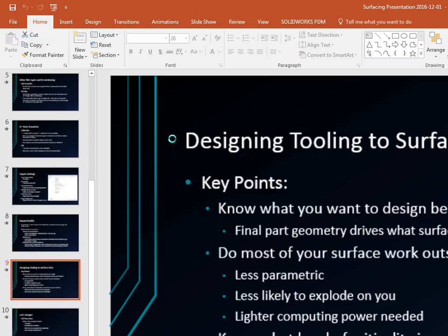That's the way you've done it, where you've trimmed all the bodies. Okay, your radius, or your variable radius. There it worked. You just select them all. That's weird. So if I did select tangent and then go into fillet, the variable radius, it's more likely to work. I don't fillet surfaces much. I usually wait until it's in the solid part. I've had better success filleting solids than surfaces.